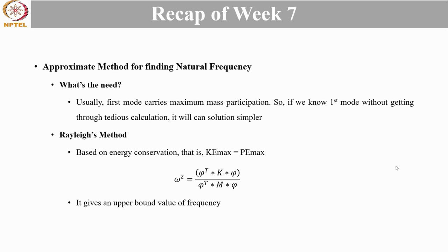For this method we also saw a MATLAB tutorial wherein we discovered that as we get closer to the actual mode shape assumption, our natural frequency value also converges to the actual one, but it is still greater than the actual one, and that's why we say Rayleigh's method provides the upper bound value of frequency.